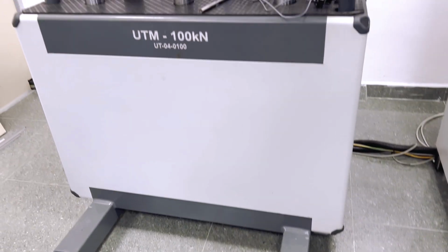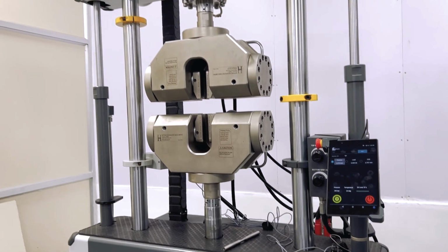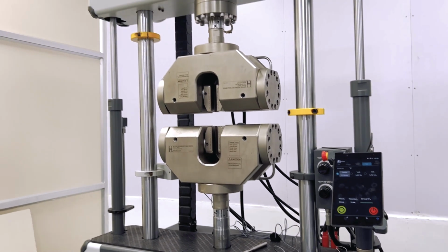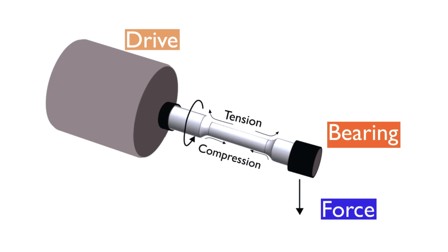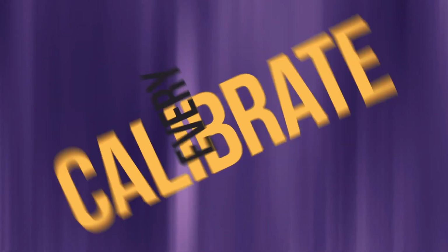Any defect could lead to premature failures. Next, you need to select the appropriate fatigue testing machine for the type of loading and frequency you want to apply. Common choices are rotating bending fatigue, axial push-pull machines, and torsional machines. The machine must be properly calibrated to provide accurate stress values.